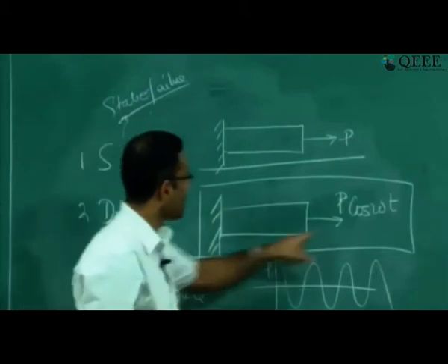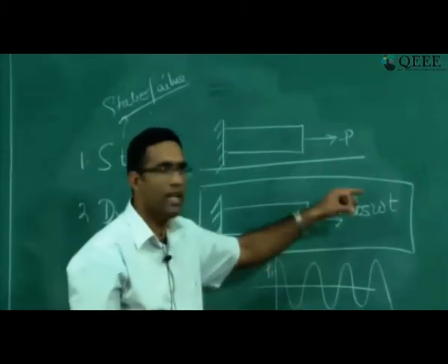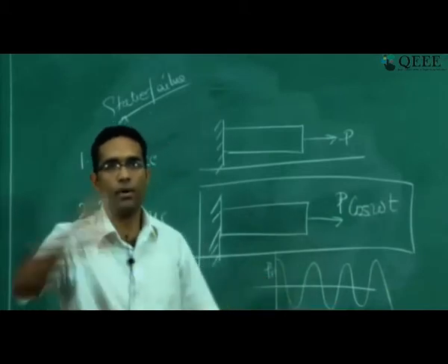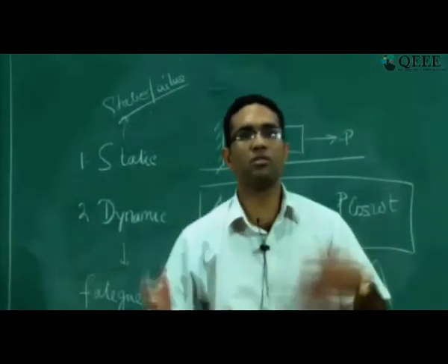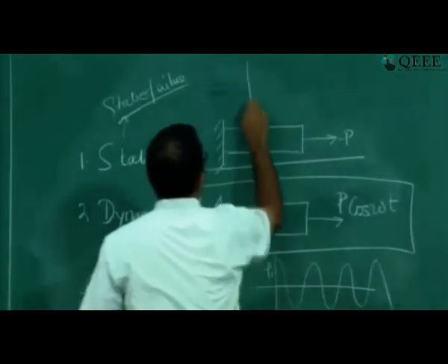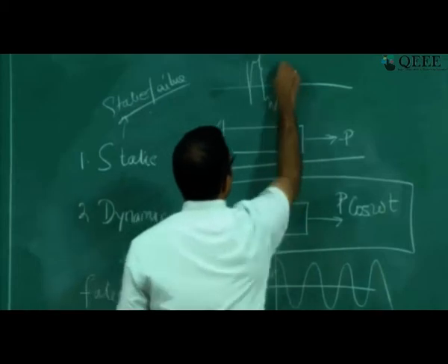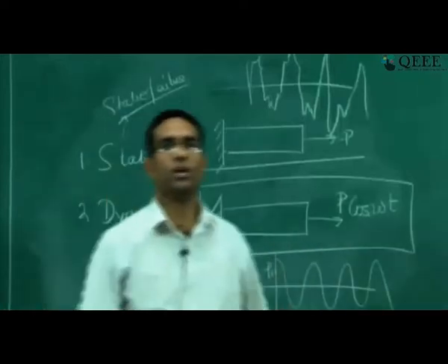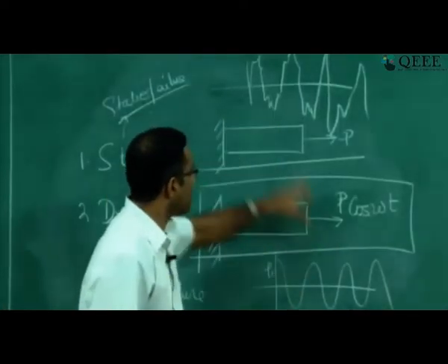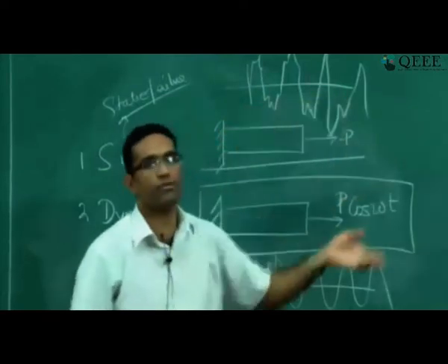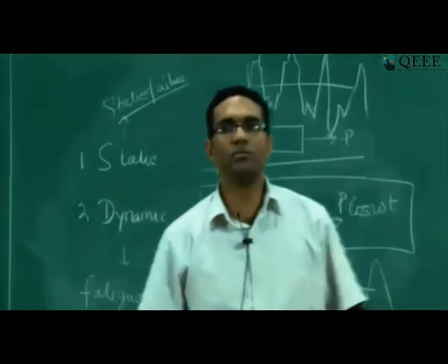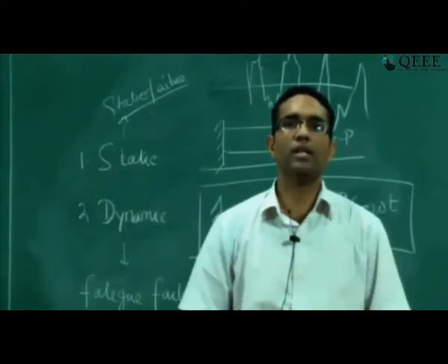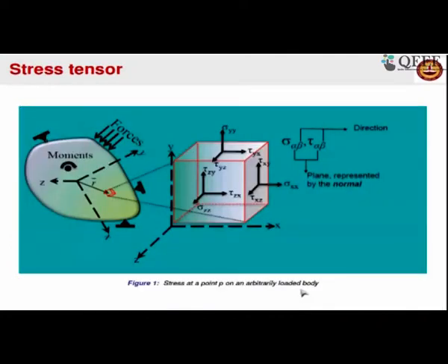Here, fatigue failure of the component is caused because of time varying load. It need not necessarily be sinusoidal or cosine. An aeroplane which is landing is subjected to all sorts of arbitrary loads. The loading on the landing gear will be completely arbitrary, it will look like noise. The basic idea is to understand that the load varies with time, and that the microstructural mechanisms which cause failure under time varying loads are different from what causes failure when the load is static. These are the kinds of things that we are going to deal with.